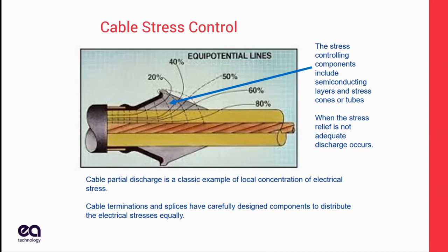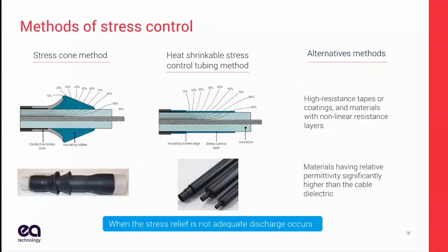40 years ago, we had tape stress cones that were done by artisans who had long internships and mentorships that were real experts at it. Then we went to cold shrink termination, or hot shrink terminations, and people use torches and that. And now we're into cold shrink terminations where anybody can do it. And that specifically is the problem. People think that anybody can do it. A cold shrink termination is a great thing, and used correctly, they're wonderful. But the problem is they appear easy to use.